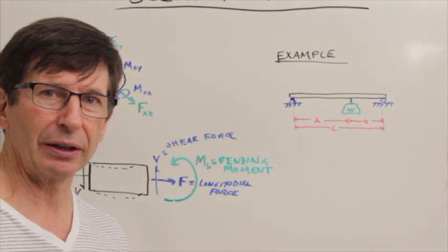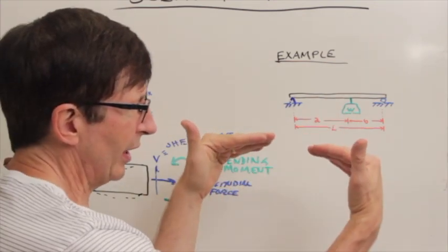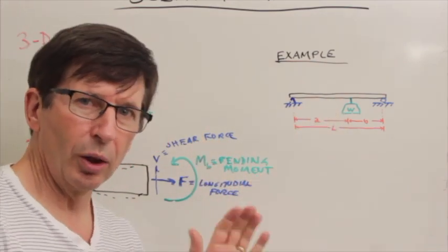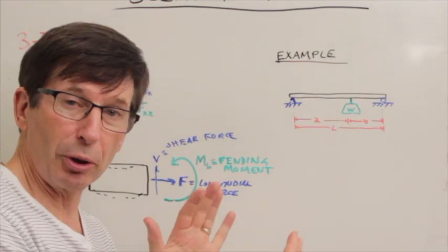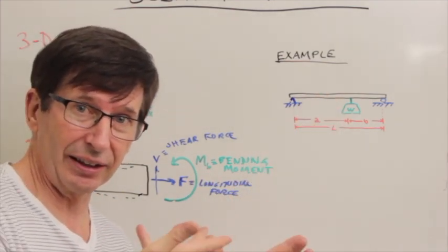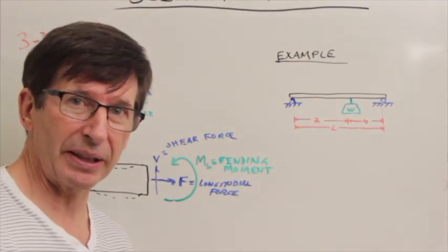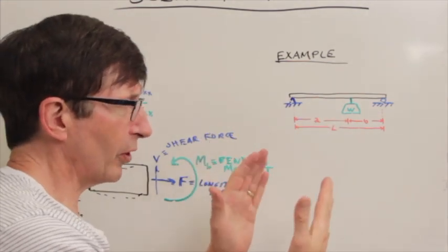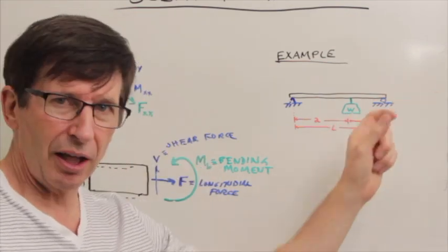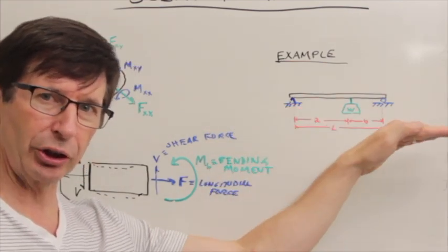And in real life, if we hang a weight W here, and there tends to be a deflection downward, well then the two ends of the beam are going to get a little closer to give us that length of displacement downward, and they will move closer together. If I fix them, I may generate a lot of force in the x direction, in this direction, to prevent that.